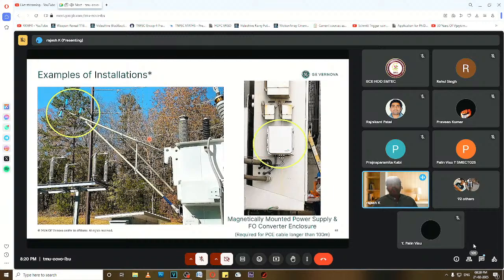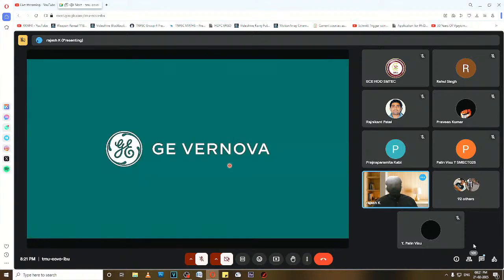Okay, and this is the look and feel of where it is mounted. You can see here this encircled area has 3 cameras which are wired all the way here. Okay, so these cameras will be monitoring the temperature across the full transformer 24 hours, and it will give vital information for us to go for maintenance. Okay, so that's all for the sensors in the digital substation, what we have in the real network.